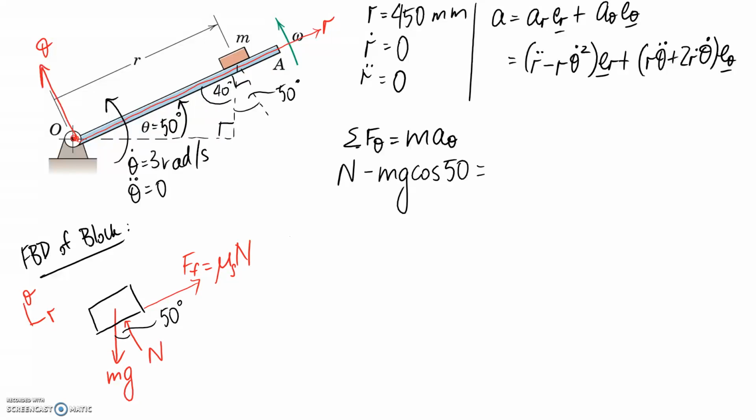Technically we could use this form of the acceleration. However, we've got a bit of a trick with this question in that we're told that this thing is going to slide down the ramp. So technically, the only acceleration that can occur is going to be in this direction, so it's restricted. That means there's going to be no acceleration perpendicular to the ramp. So instead of using this equation, we know that it's going to be equal to 0. No movement perpendicular to the ramp, so the mass times acceleration here has to be equal to 0.